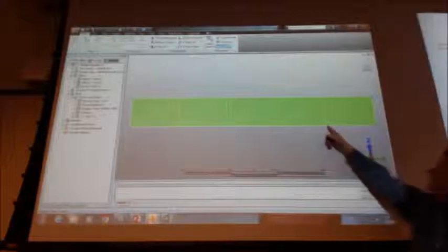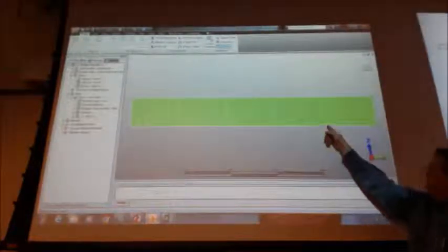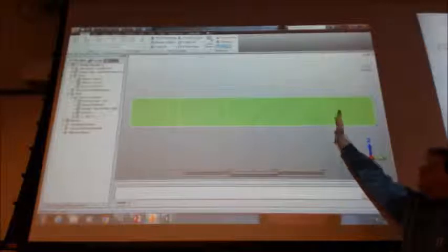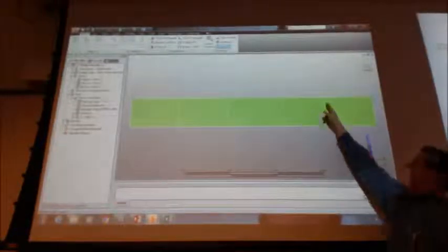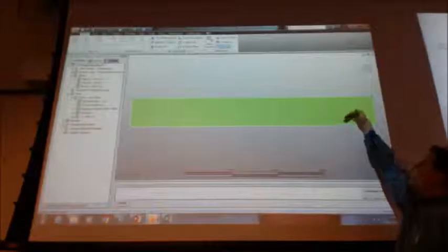Okay, so what you don't want is one element spanning your shape, right? You have to have at least 2 elements to span your shape. Otherwise, you don't get good transformation, right? Because from here to here is one element edge, and so wherever this node is, it's going to move as 1. So you need to have at least 2 layers of elements.